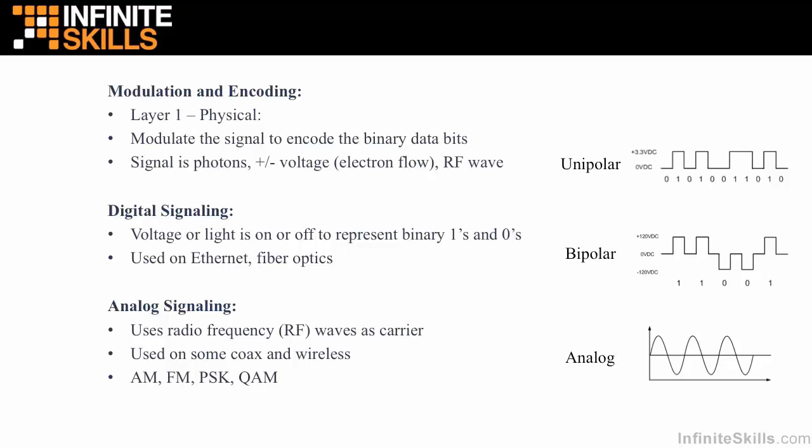And instead of carrying upward forward as my sine wave continues, suppose I reverse that wave and I go down for a half a wave. And by shifting the phase 180 degrees, I can represent a binary 1. Or if I don't shift the phase, I represent a binary 0. So here is phase shift keying, another technique for modulating a radio frequency or analog signal wave and encoding